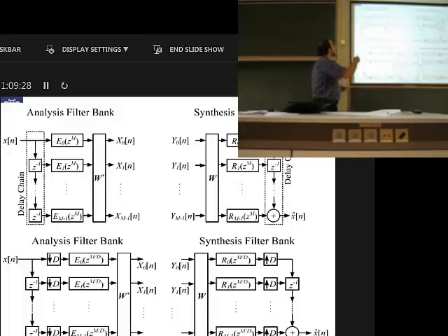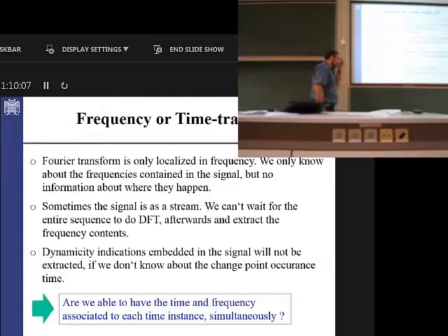So it means that the convolution or the multiplications of each of these paths is actually reduced by a factor of d, by just replacing these downsampler and the filter and taking the polyphase structure. So it has the effect of d times less multiplication for each of the paths. And you have here, for example, m number of the paths or d number of the paths. You have d number of the paths. So that's why we can implement the filter bank much faster.